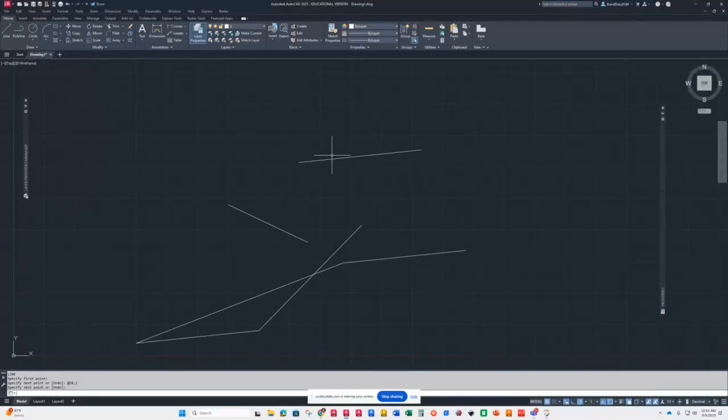The first point can always be absolute. But when I turn that on, now I don't have to put the @ symbol to make it relative. So then if I go to line, and I wanted to make a polar coordinate, how do I make a polar coordinate?